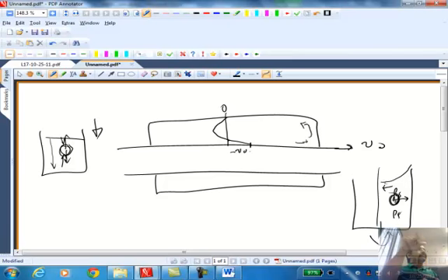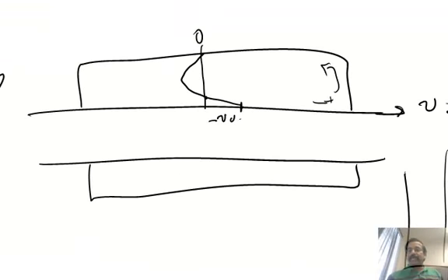You have to integrate the pressure, right? And in this case, the pressure variation is linear, but in the centrifugal case, the pressure variation is quadratic. Okay, so you need to rederive that particular formula. But here I'm just asking you qualitatively. So qualitatively, if the particle is lighter than the fluid, then the centrifugal force it experiences outwards is going to be smaller than the pressure force that is exerted on it.